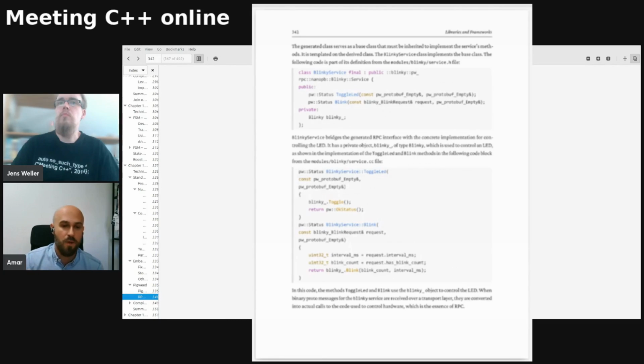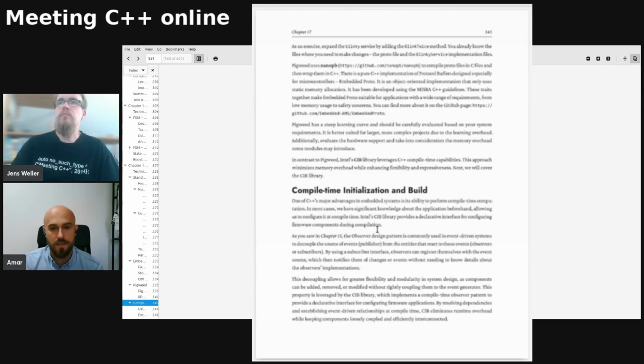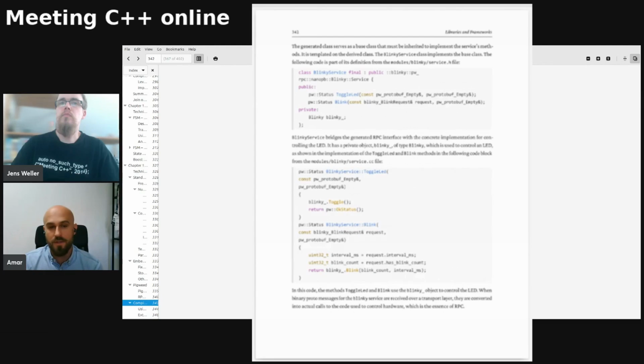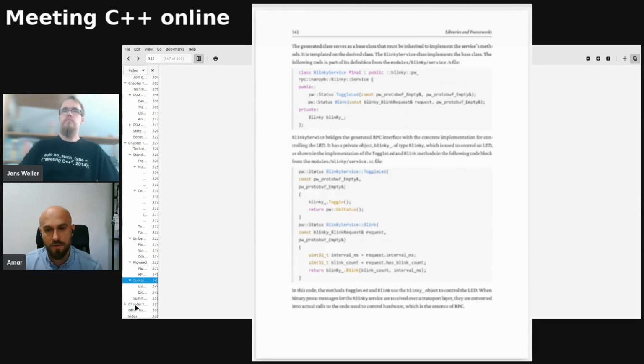One is while you're doing development, you occasionally want to test some functionality on target. And if you are working with really complex embedded systems, you want to be able to trigger that behavior immediately without waiting to go through certain scenarios or whatsoever. So the RPC allows you that, so you can trigger certain function call or functionality on your target from a console.